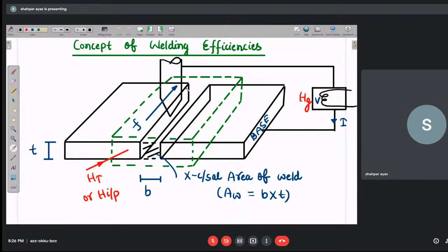Now, some students have this confusion in mind: sir, when we have the requirement of only 300 joule to melt these surfaces, then why are we not transferring 300 joule by the transformer? Because everyone knows 100% efficiency is not possible. If your need is 300 joule, you cannot produce exactly 300 joule, because we cannot transfer 100% of the energy. There will be some losses, and various factors are there in those losses. So that's why it is not possible. Take care of this.